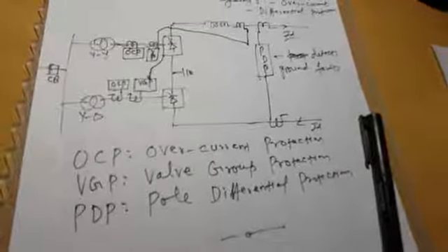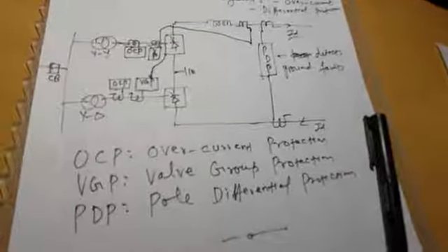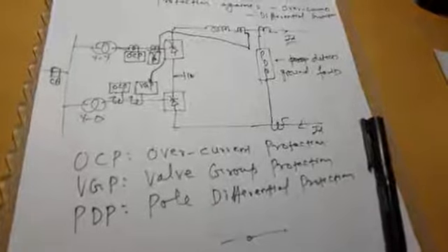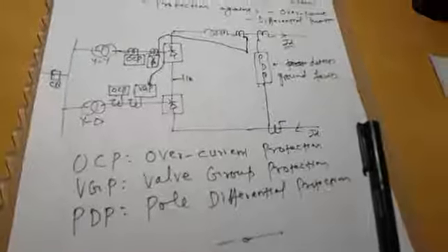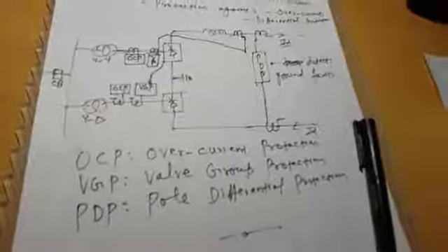And finally, switching off DC filters and paralleling of DC poles are also responsible for overvoltages in your HVDC converter stations. And the third cause is converter internal faults, energization of poles, or stray inductances and capacitance. Converter internal faults are also responsible for overvoltages in your HVDC converter station. Then overcurrents are because of faults like short circuits or ground faults, etc., and maybe overloads also. Therefore, you have to provide overvoltage protection and overcurrent protection.